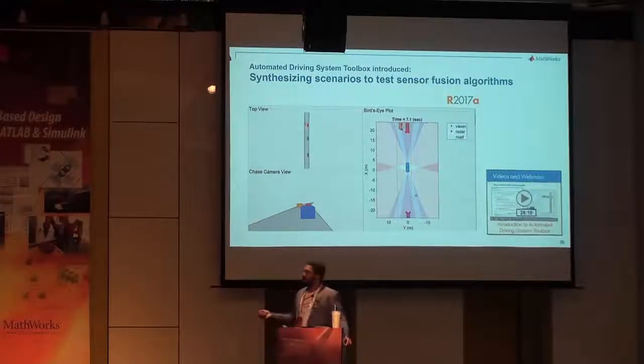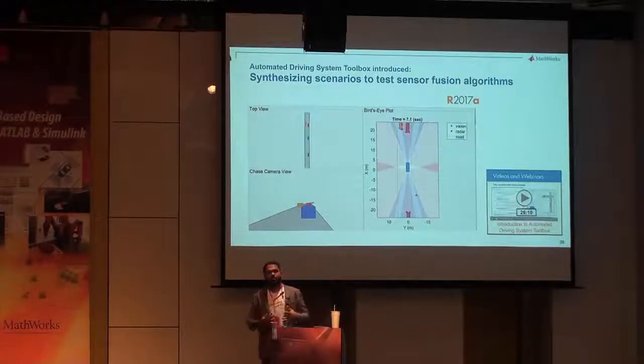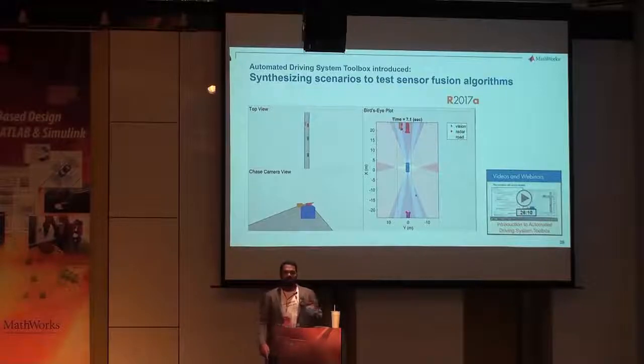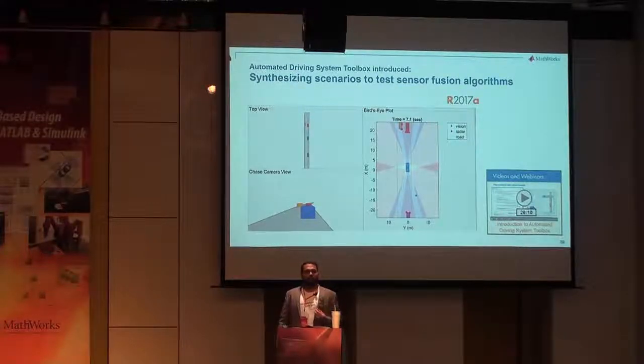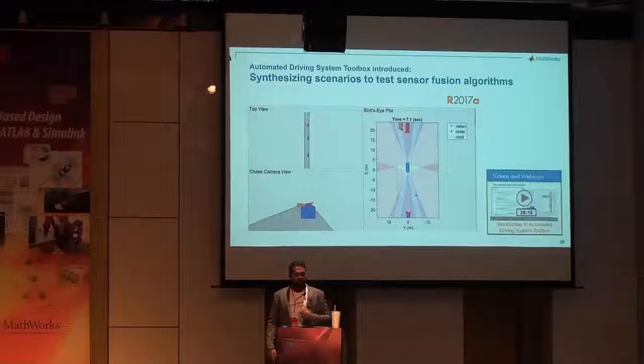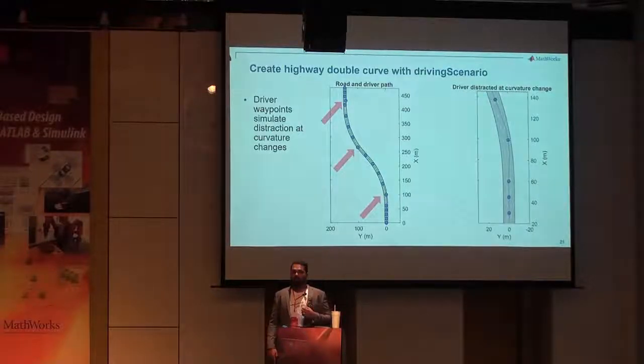And this is why we've designed a scenario generator in MATLAB, in Automated Driving Toolbox. You can design a 3D scenario like you have here, where you have your ego vehicle, and you can decide other vehicles and roads, and you can design it in such a way where certain actors are moving according to predefined paths. And with that, they also generate synthetic detections, as if there was a radar on your vehicle or a camera, giving you detection outputs. So that lets you design a scenario and test it.